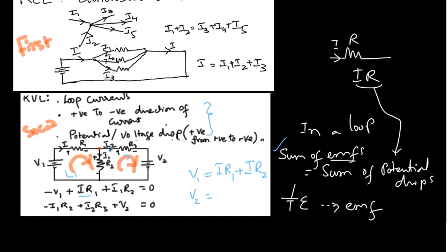Therefore if you are in the opposite direction, you will just take I1 R2. Opposite direction you will put a positive thing. Same direction you will put a negative thing. So this is in the same direction, that's why you have put I2 R3. Okay. So this part of the confusion, normally you will not get, but in case you get, this is the other way of telling.